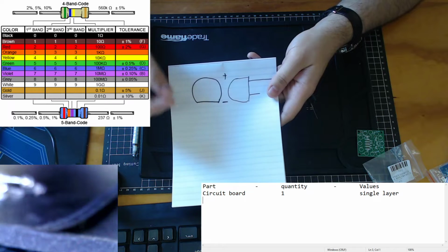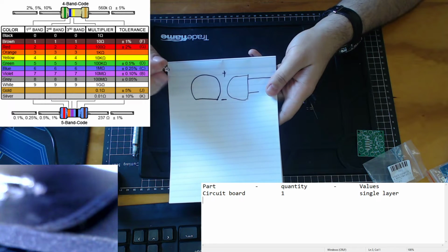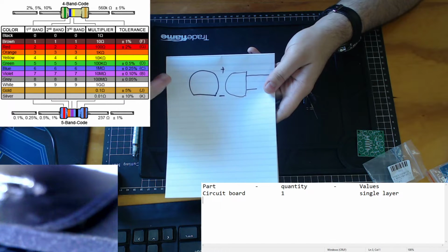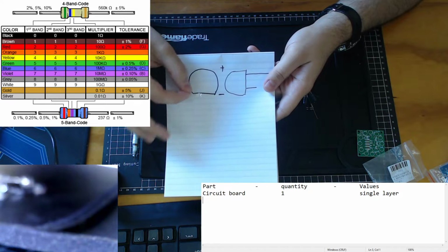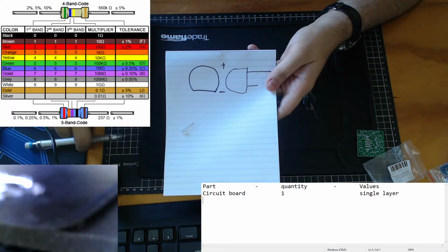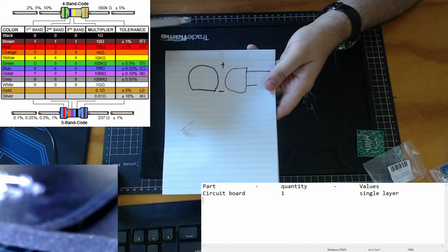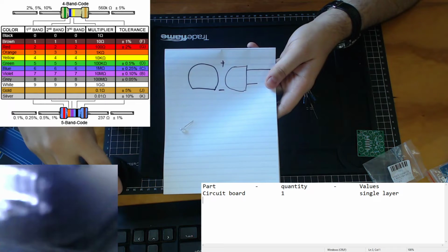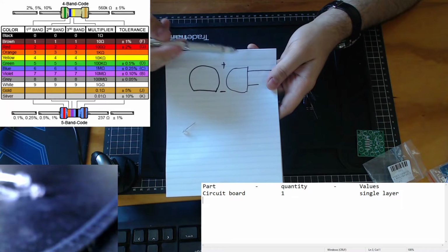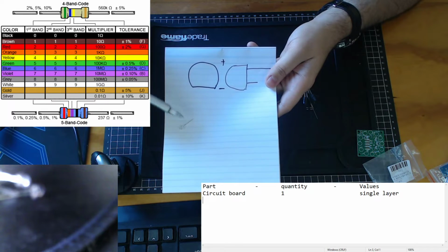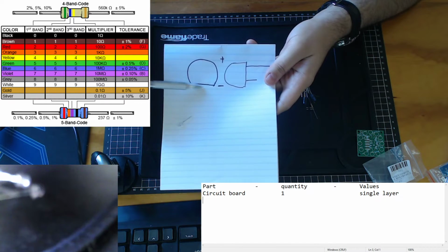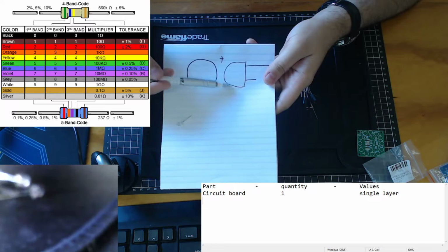And so we know that LEDs are polarized. They only work if the current's flowing in one direction. So they have to show some sort of indication on the actual LED light itself to do this. So what they do is, when you have your component, the long leg itself is related to the positive. But the issue we have is, once you solder it onto a circuit and you cut down the size of your legs, you're not going to tell where the longer leg was. So they also make it so the flat side of the LED light is related to the negative.